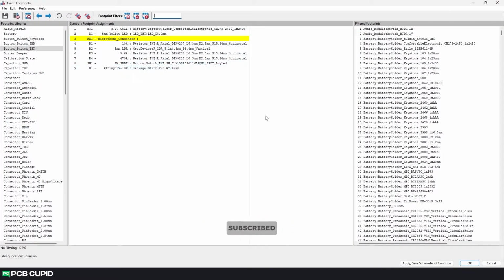Now we are at the tricky part. We don't have a footprint for the condenser microphone in KiCad. In this case, I would usually either download a custom footprint or make my own footprint using a footprint editor. Since we never discussed that yet, we'll try to find another symbol with similar shape and dimension and replace it for now.